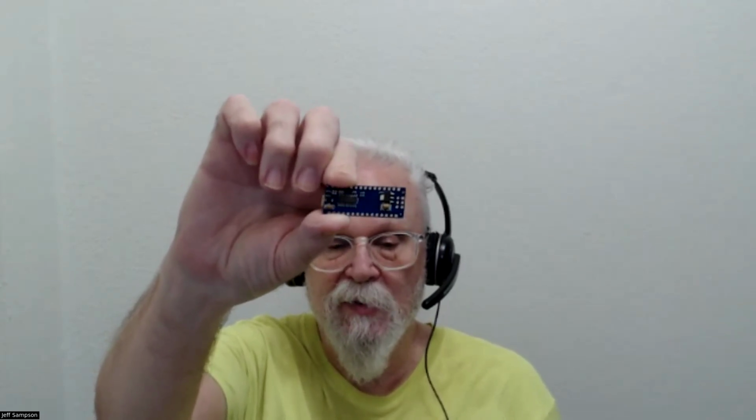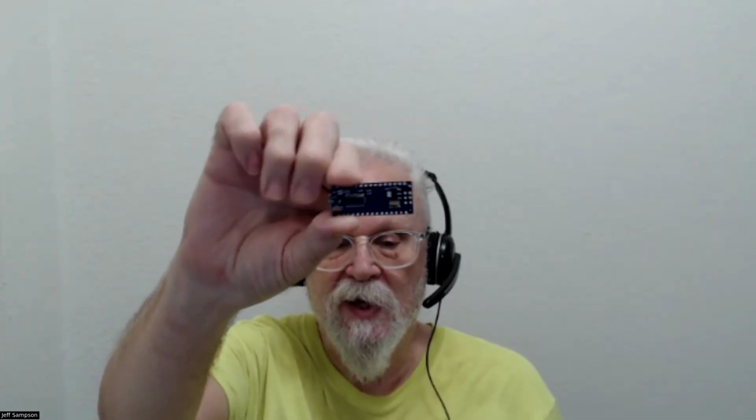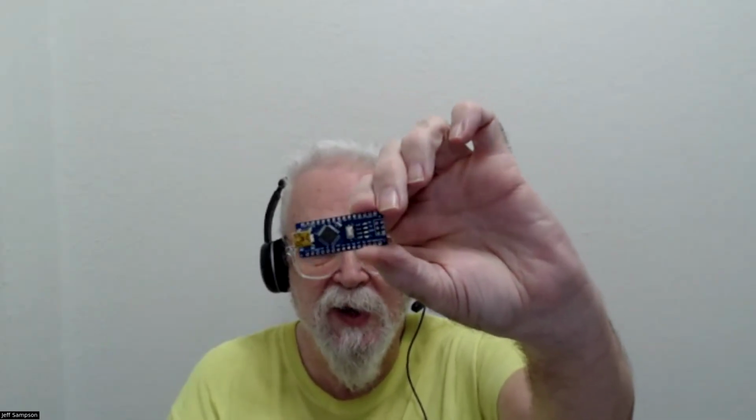Anyway, it's like an Arduino Uno, but they just put it in a small form factor, and it's got a USB connector, and on the back it's got an FTDI adapter chip. So this works just like an Uno. You plug your USB cable in, you can program it, you can use the serial port on it. But if you want to put this in low power mode, this chip on it happens to be the ATmega328P, P standing for pico power. So this is meant to be something you can put in low power mode.